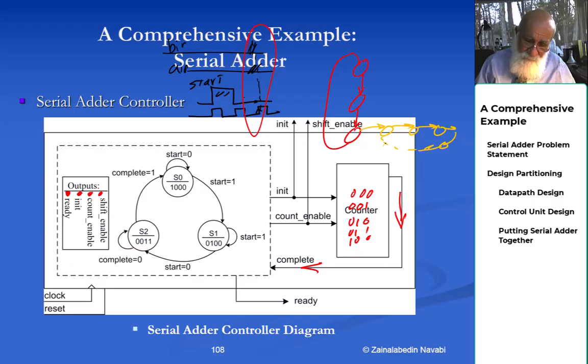That means when it gets to this last state, S2, a counter, remember counters are state machines also, is activated, and then this state waits in this state until the counter tells it that it has counted. So I have 2 state machines, one is activated by the other one, and in some controllers you may have even more state machines, but this is a good example of having 2 state machines working hand in hand.